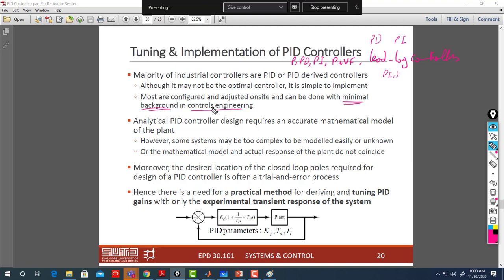I gave the students last year a self-balancing robot and asked them to tune it. It's very hard to tune. If you go to the lab and try to tune the inverted pendulum, or any unstable system, it's very hard if you don't have a model and don't do some simulation beforehand. You need a starting point from which you can start tuning. Otherwise it's going to be very hard to find the best configuration of 3 parameters.